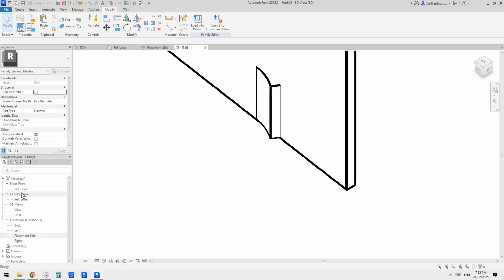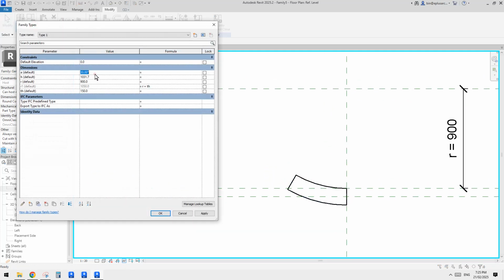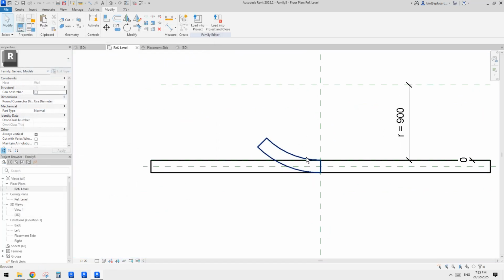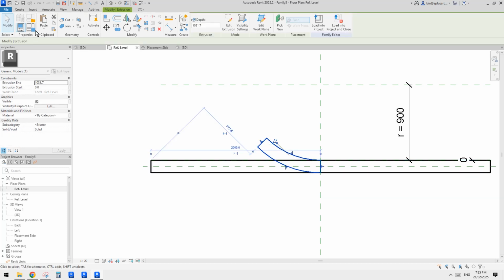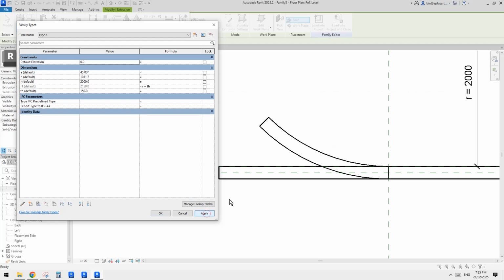there. So let's go to floor plan again. So I'll just roughly increase the angle, so at least we have some space for that planter box. Oh, hang on, is that right? Let me show the wall. So if this is the wall, yeah, I think that's the wall face, that's correct. We just need to increase or reduce the radius, or I'll just reduce this one to 2 meter. Apply, yeah, so at least we have slightly bigger space.